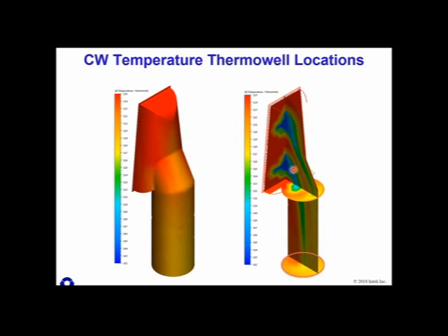And so we recommend doing a cooling water analysis. You can find planes in this stratified area that will give you the best chance at getting temperatures within a few tenths of the true average. That's how we recommend doing it. The shortcut is to just pick the furthest downstream that you can possibly lay your hands on and put an array of outlet temperatures there.